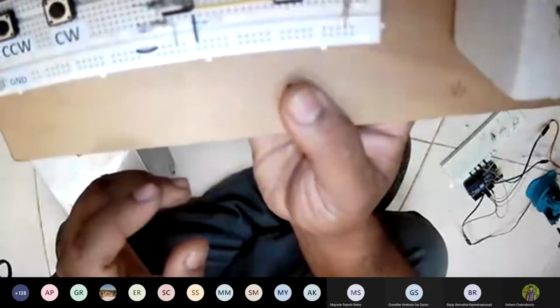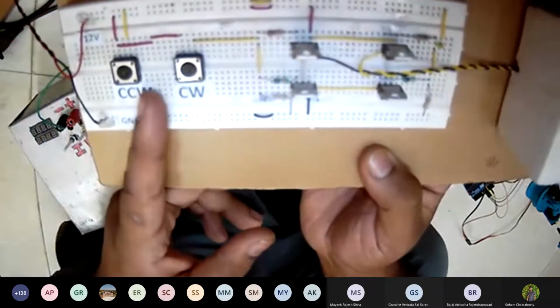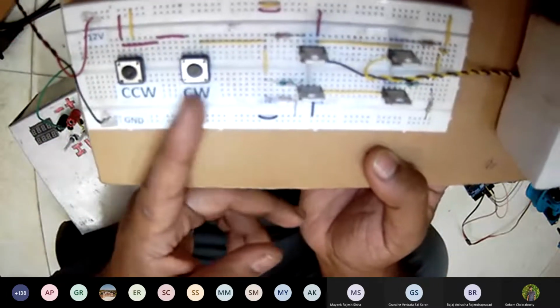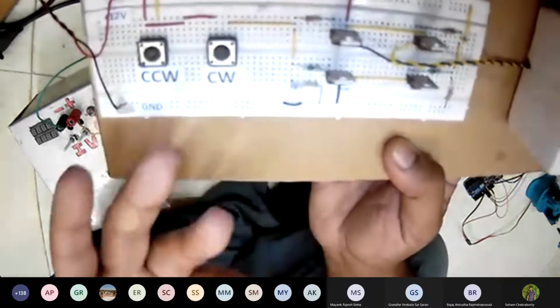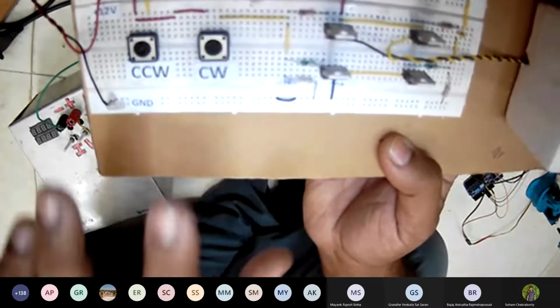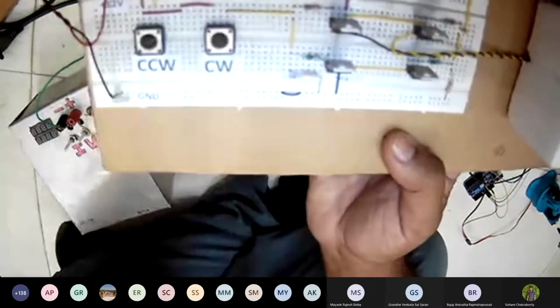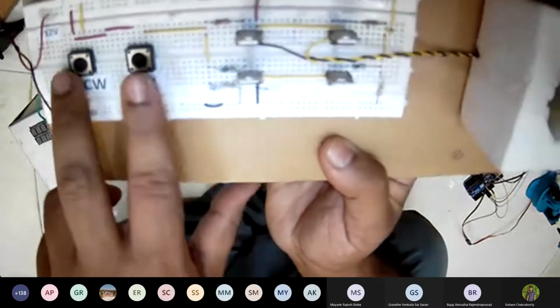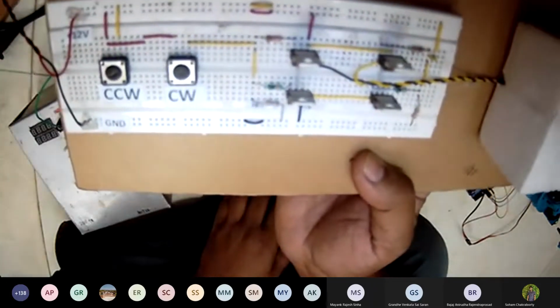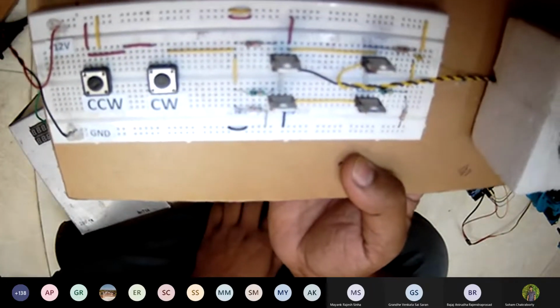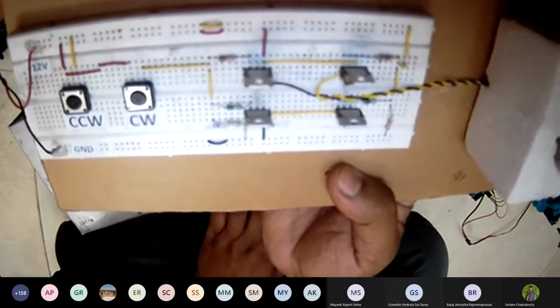Okay, so over here, because I did not have a SPDT at hand, I have used two switches. And I'm never going to press both of them at the same time, because the moment I do, these transistors will blow. They will go into thermal overload and they will be damaged. I mean, there will be magic smoke. So we don't want that.